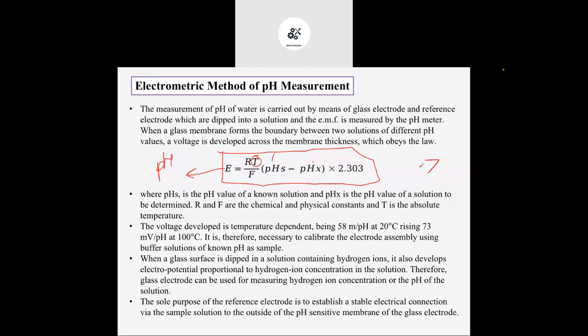Because it will indirectly affect the life of the power plant and the different devices. As we saw, the acidic nature of the solution increases the rate of corrosion. Similarly, the basic, alkaline nature of the solution causes the precipitation of scale, and that will again give us problems inside the boiler tube, or it will reduce the life of the boiler tube and also the condenser tube.